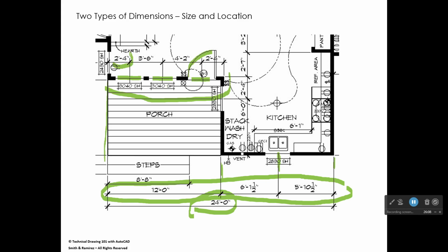Well, here are your dimensions. We actually are going to have to place our dimensions on the inside of the floor plan to get all those guys in there. Okay, so when you're dimensioning architecture, a lot of times you're just trying to fit your dimensions in where it's clear and people can read them easily. Okay, so these dimensions tell us where the centers of a 3-0 window, another 3-0 window, and the center of a 3-0 door are.